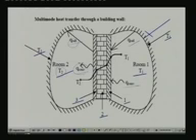Okay, so look at the picture carefully. Now we can also draw the temperature profile. For example, if this is the temperature T1 of room 1, and let us assume that this temperature is uniform in the room, then there will be a temperature drop at this point because of the convective and radiative resistance. There will be a further temperature variation within the wall because of the conductive resistance. So the temperature profile varies like this. Again, from the wall to room 2, you have a temperature variation because of the convective and radiative resistances of this room. Okay, so this is the typical temperature variation for this particular problem.